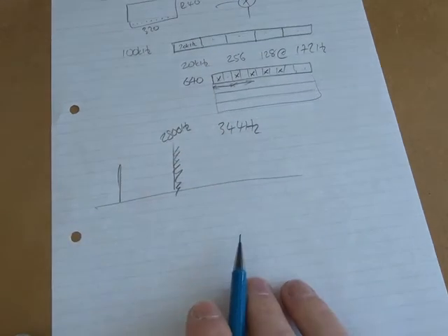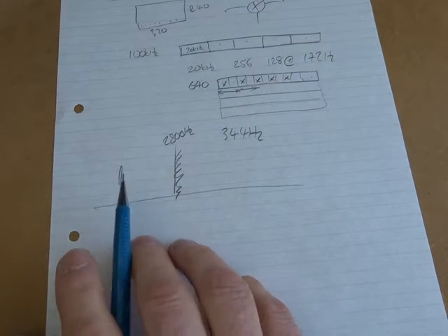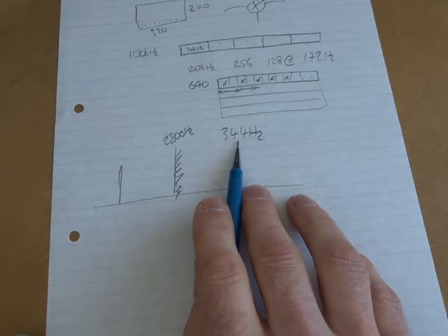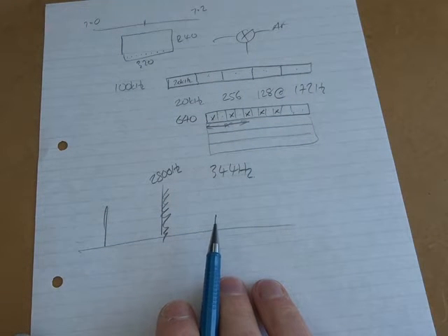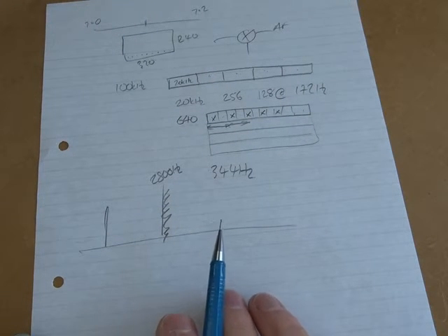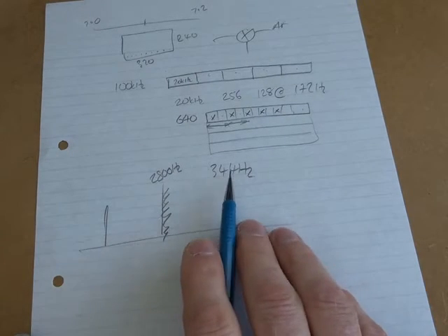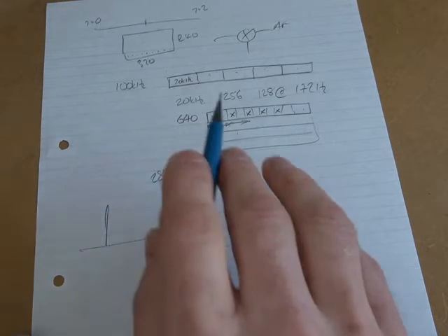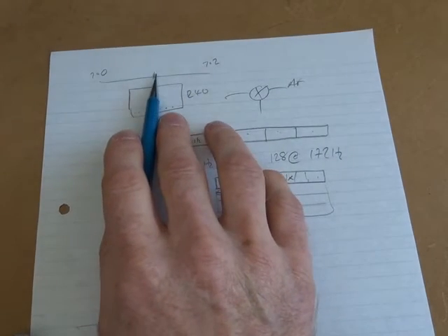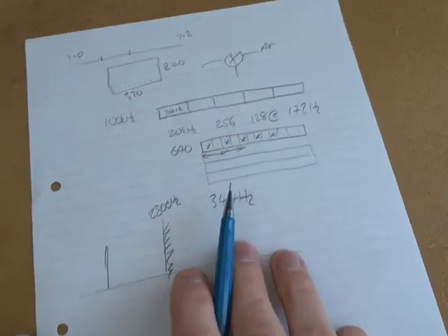CW is going to be a different story, being more discrete, and potentially I might actually miss some of those with a resolution of only 344 hertz per dot, or per pixel more to the point. So we'll just have to see how that one plays out when I actually go through. That's what I'm currently thinking. If the resolution is not fine enough, then the next option would be to drop our analysis down from 100 kilohertz bandwidth to say 50 or something else.